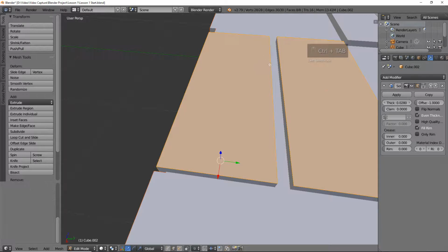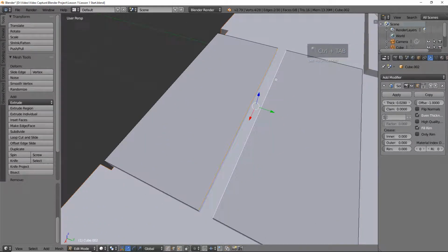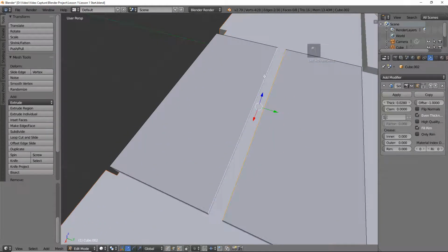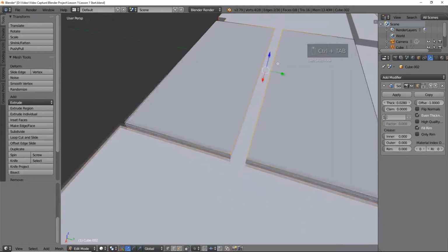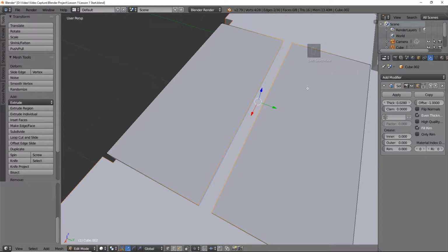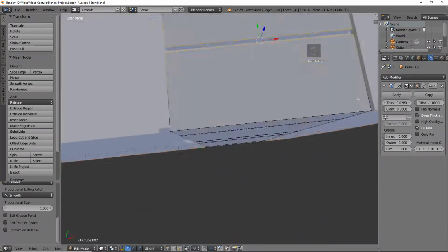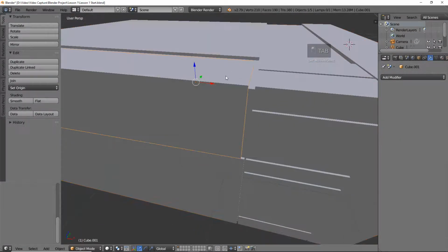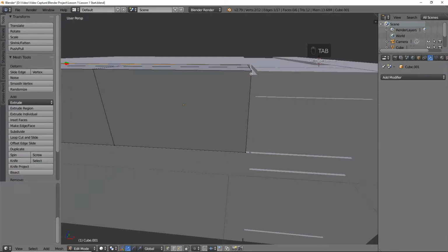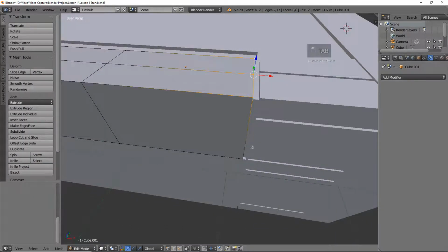The top looks a bit too big, so let's just select the edges. We are then going to convert this selection from edges to vertices by holding Ctrl and selecting vertex. Not that we have to make this conversion, but I just thought I'd let you know how. So we scale it in and match the size a bit better. Press Tab to exit edit mode and let's select the door and adjust the gap here as well by selecting the vertex and bring it over to the right.